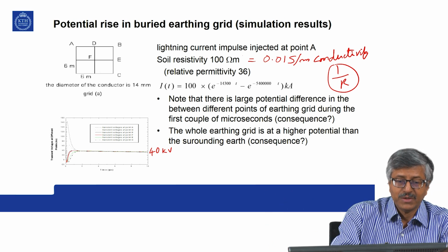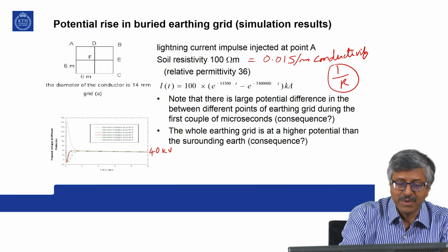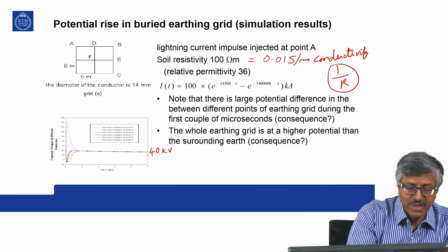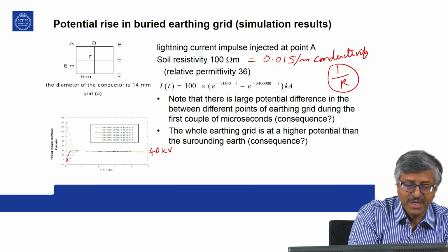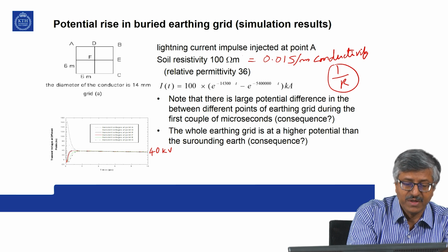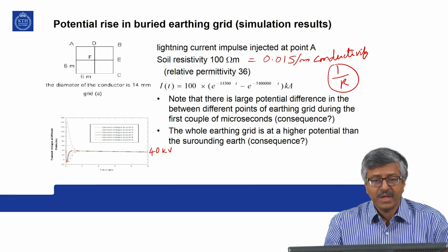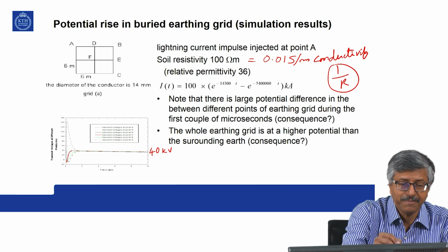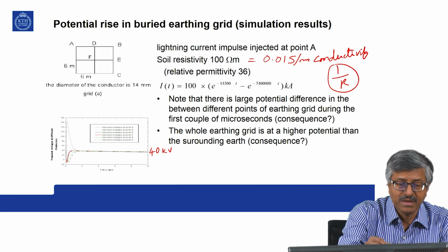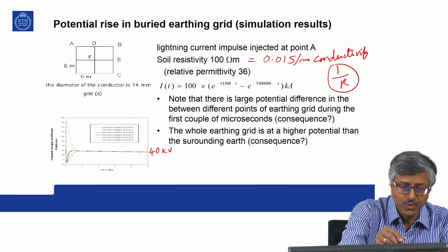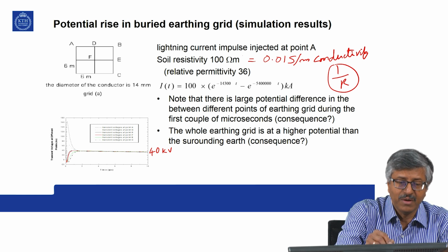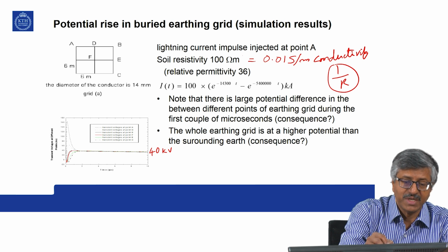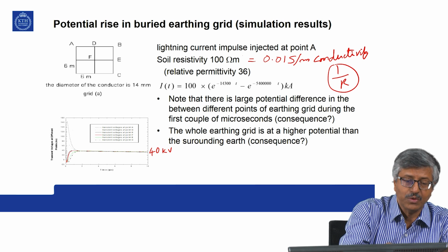systems. So, now here it is more or less equipotential, but again at a higher potential level during the lightning strike, and during the first couple of microseconds you do not have any equipotential. So, one has to be aware of this. If you have one system connected here and another system connected here, then through the cable of the systems you can have very large currents flowing because of the potential difference between those 2 points during the first 2 microseconds.